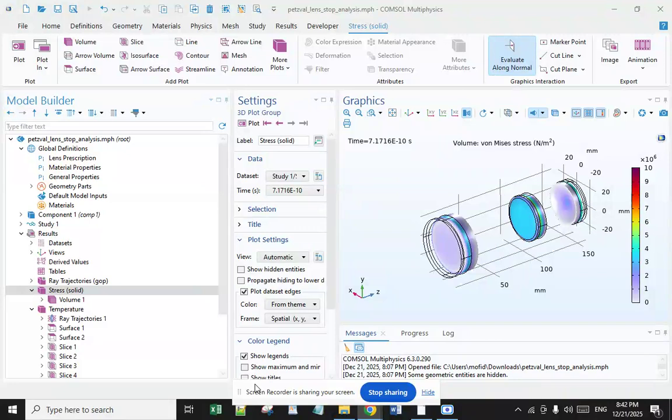the imaging payload. Similarly, any slower frequency vibrations from satellite components, such as deployed solar panels, can add further dynamic effects to the optical payload if the optical payload is not isolated effectively from these dynamic effects. These high and low frequency oscillations can impose undesirable dynamic effects on the optical payload and in turn degrade the clarity of the image produced.